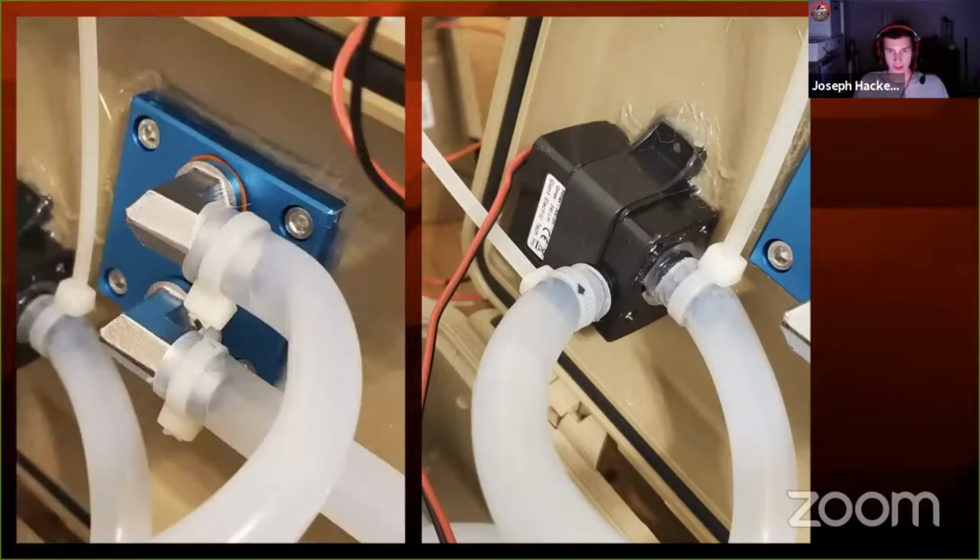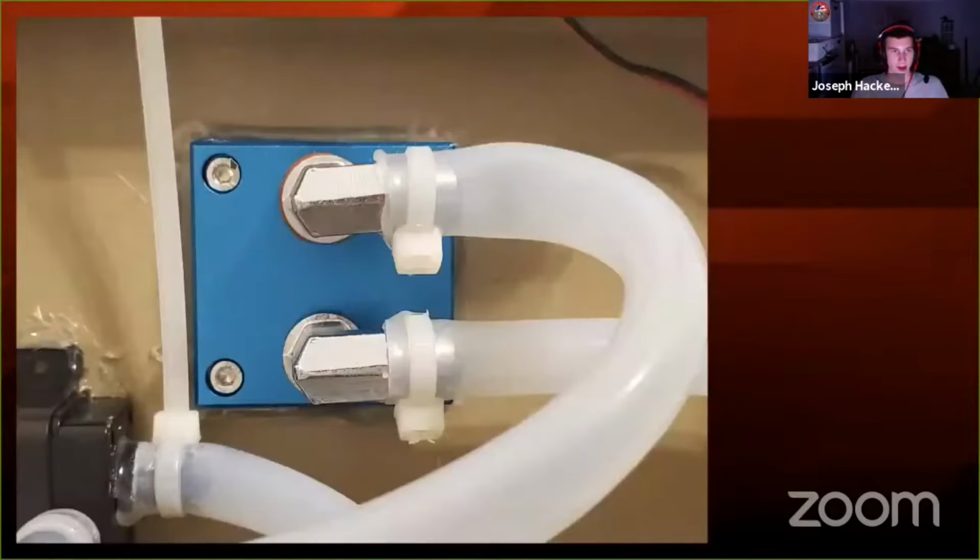Then it comes out of the pump into this little blue rectangle, which is actually a CPU cooler water block that I got from Amazon. One side of it is made out of copper, and it actually passes water through. You can see the 2 hoses on here. You put water in there, and it comes out the other side, and it takes heat with it, which it would for a CPU, but I'm actually using it in reverse, so it's leaching some of that heat out, and it's putting it through the case of this Pelican.